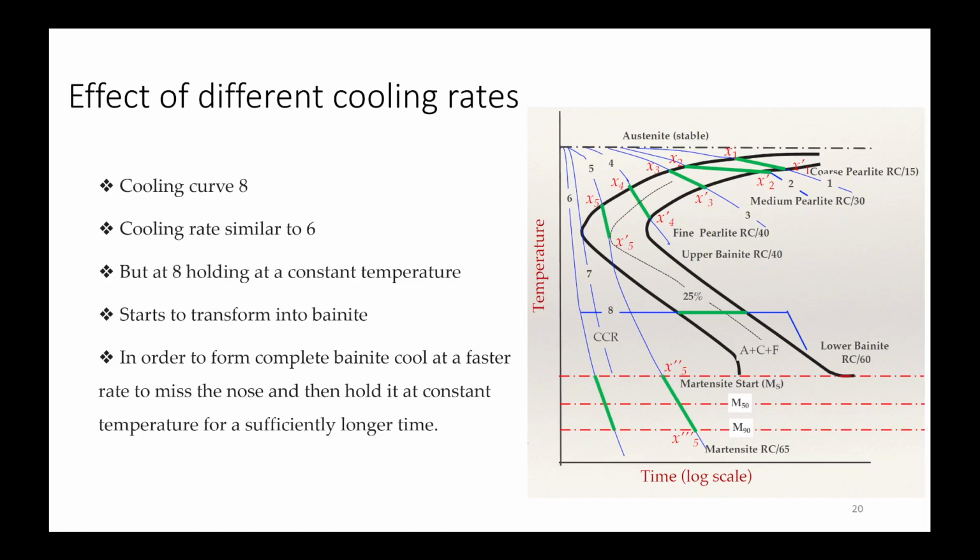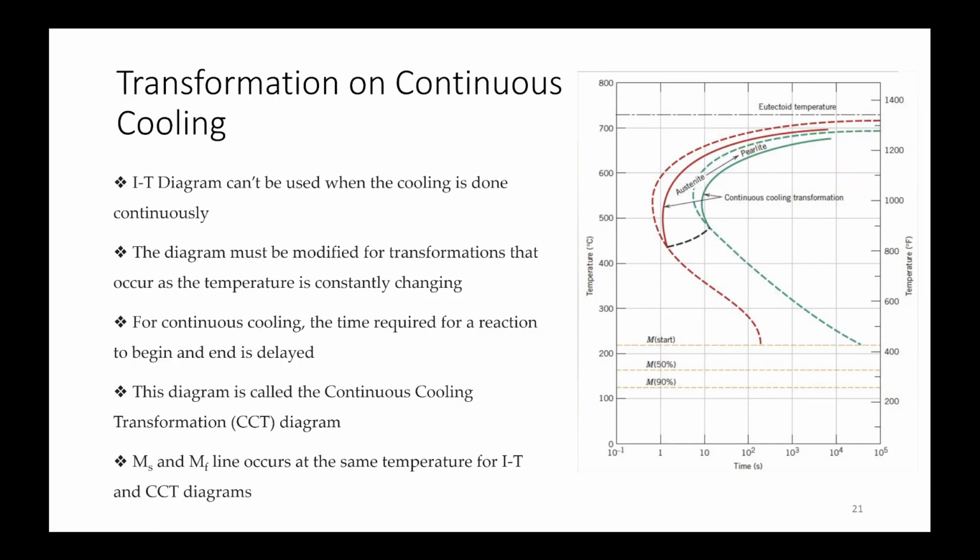Ma'am, can you briefly explain cooling curves to phase diagram? Like how we will be drawing that phase diagram from cooling curves for the binary alloy. In the cooling curve, the temperatures T1 and T2 are given in a slanted position, and when we are drawing the composition-temperature graph, it's given as a straight line.